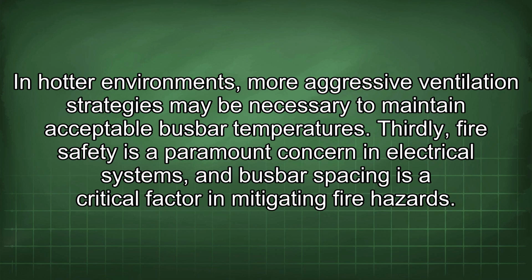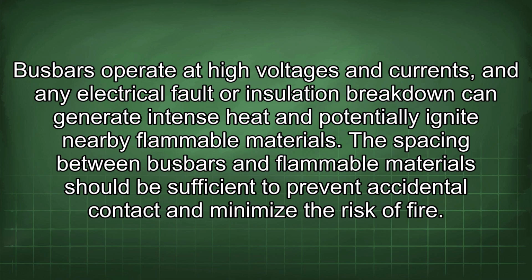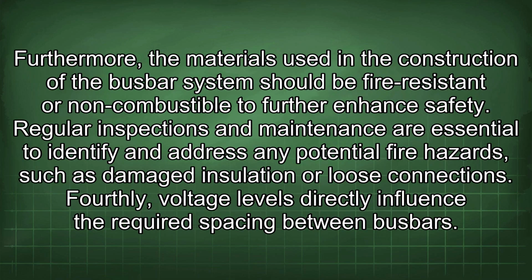Thirdly, fire safety is a paramount concern in electrical systems, and busbar spacing is a critical factor in mitigating fire hazards. Busbars operate at high voltages and currents, and any electrical fault or insulation breakdown can generate intense heat and potentially ignite nearby flammable materials. The spacing between busbars and flammable material should be sufficient to prevent accidental contact and minimize the risk of fire.